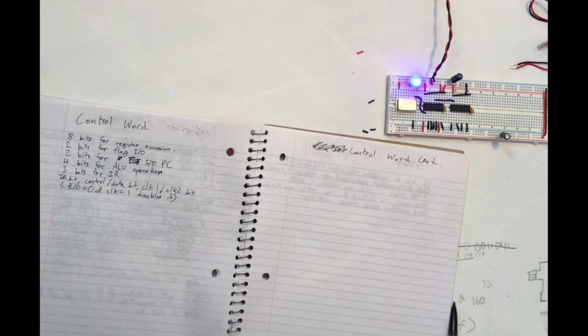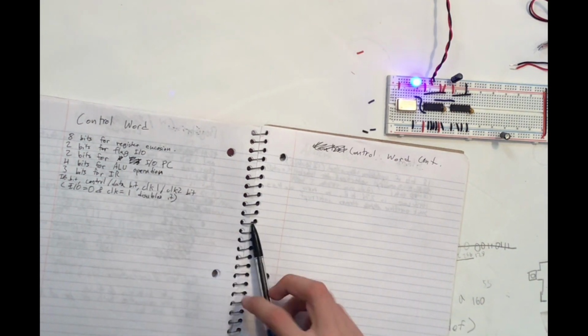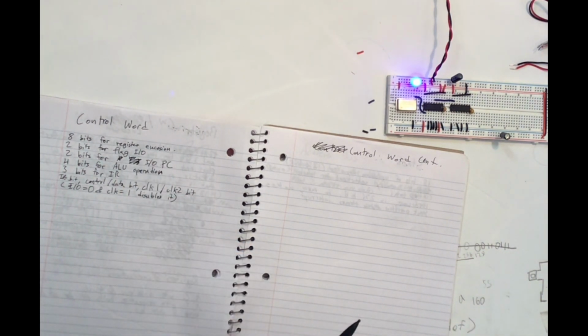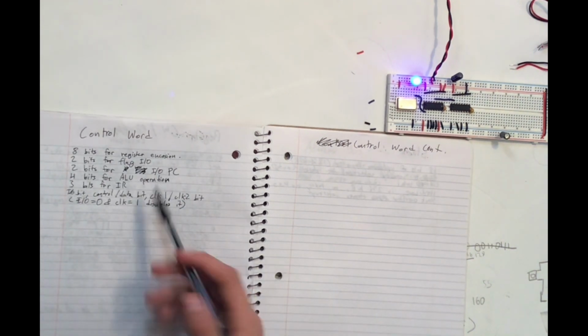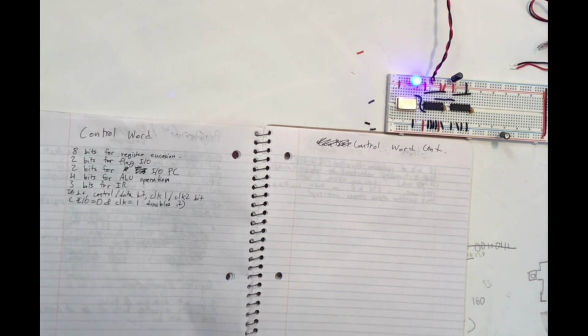There's going to be the flag input output for like push F, push the flags, the program counter output and input. The ALU operation is actually going to be in the control word. So like addition and subtraction will be in the control word, and then further deciphered in the ALU, but that will be from multiplexing, so it will be fairly fast, or demultiplexing. And then we have some bits for the instruction register in there, control data versus data bit, I/O bit, and there's going to be clock bits and stuff like that. That's going to be port stuff.